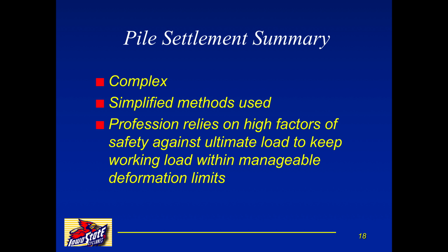So in summary, pile settlement is very complex. A lot of simplified methods are currently used in the profession, and typically the profession relies on high factors of safety against ultimate load to carry the working load with manageable deformations. In class, I'll work a couple of examples and also give you more handouts.